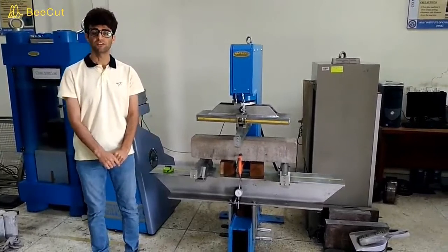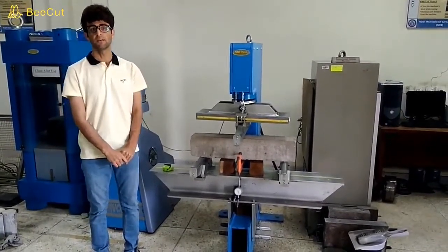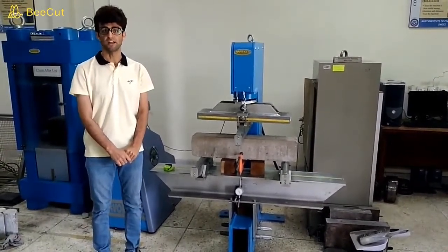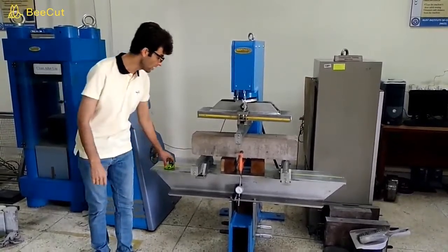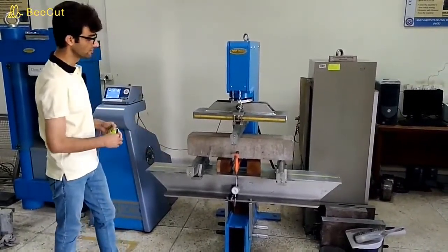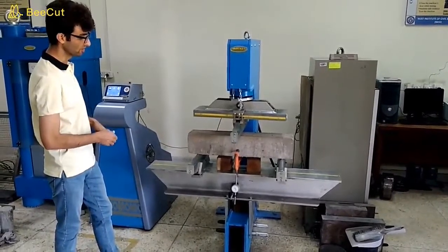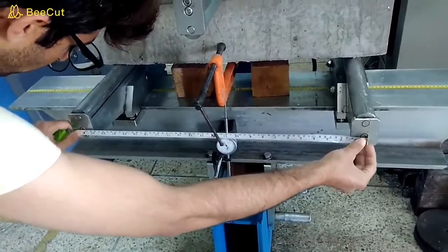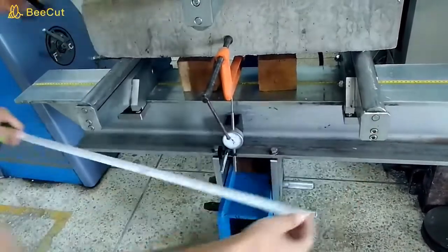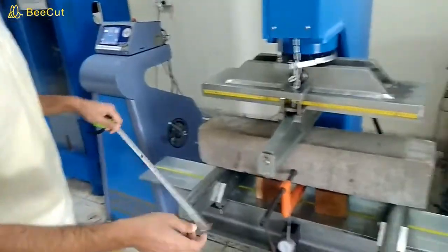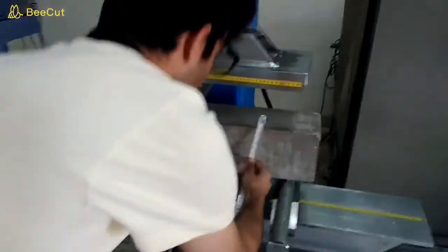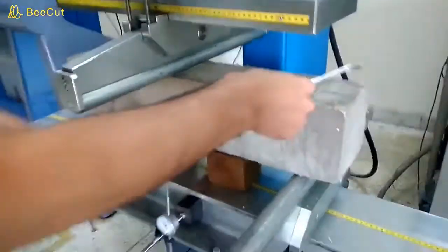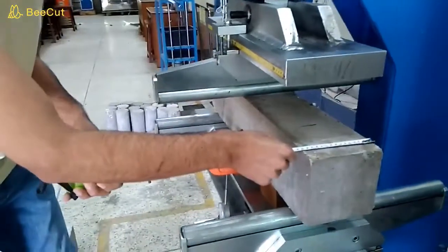The procedure of this experiment is covered in ASTM C78. Here we can see that we have to place the simple PCC beam in the flexure testing machine. First we have to measure the center to center distance between the supports, which is around 700 mm. Then we measure the height of the beam, which is 150 mm, and then the width of the beam,